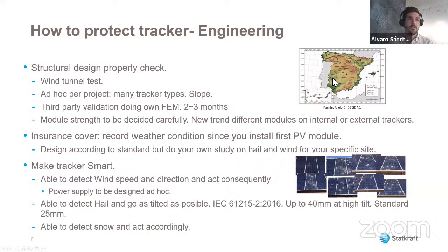So we consider it very broad. We always do our own hail study and also a wind study specific for our site. But afterwards, we do the design according to the standard, just to be covered. And in case we have any issue, we can prove that we have done the calculations according to the standards. But in general, the wind speeds for our sites are lower than in the standards.